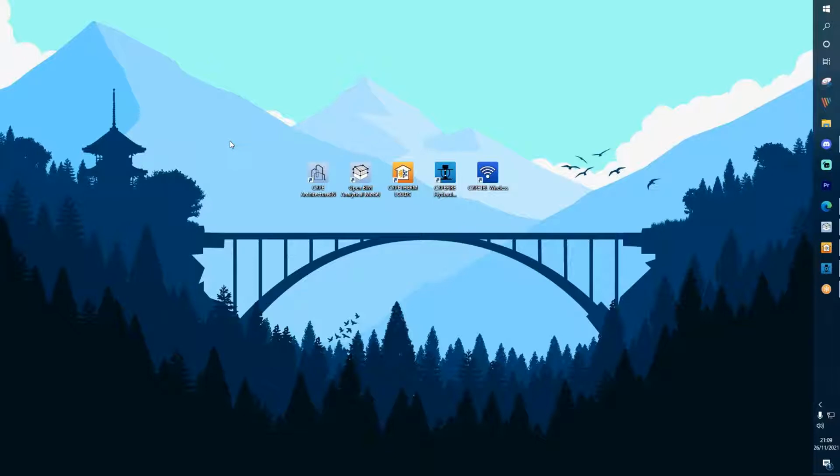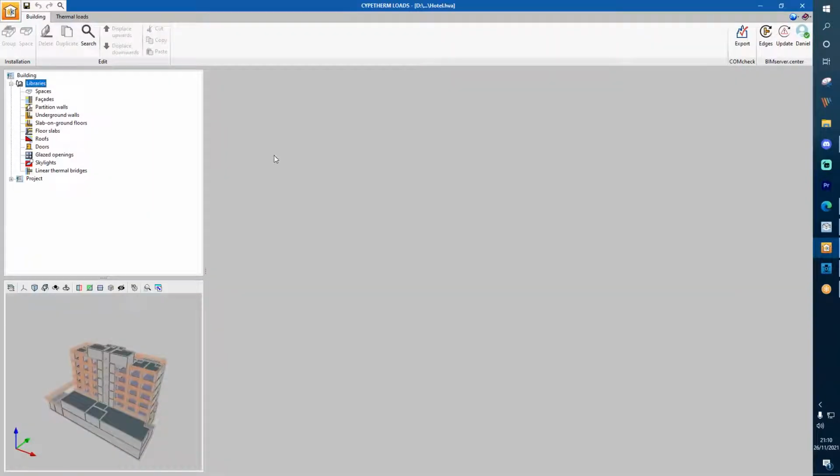All right, thank you, James. Hello, everyone. As James said, my name is Daniel, and we are here because I would like to show you some programs that are included in the OpenBIM workflow for the MEP solutions. And the first program that I would like to show you is the thermal loads program that I have open here. The thermal loads is a software that allows us to calculate the thermal loads in buildings that uses the radiant time series method proposed and recommended by the American Society ASHRAE.